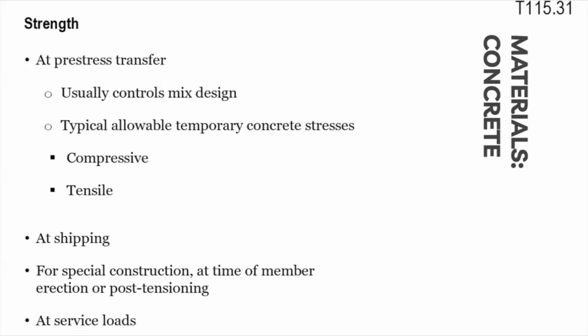However, in regions with bonded tendons or reinforcement, the limit is 0.24 times the square root of F'ci, with bonded reinforcement proportioned to resist total tension calculated assuming an uncracked section at a steel stress not exceeding 0.5 Fy and 30 ksi.